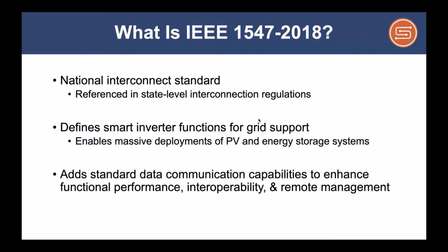Secondly, we have the issue of interoperability. These DER systems are now grid supportive, and so if one is removed or replaced, we want another system to be able to stand in its place without the need for further re-engineering of the network. And so 1547 provides interoperability for that purpose. And then finally, remote management. Things will occur, things will need maintenance, and when you have a standard communication network, you can do many of these activities to maintain systems from a home office. So remote management is another key component of IEEE 1547, and the data communication that comes with it.